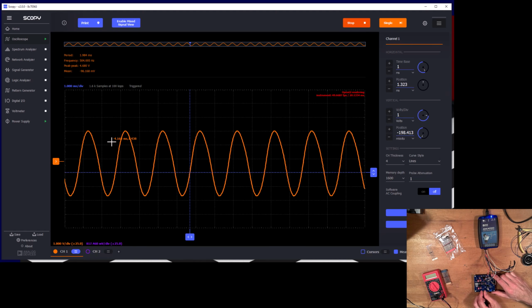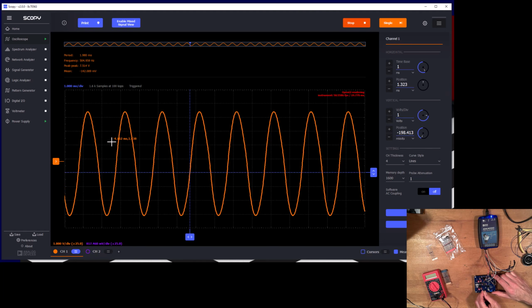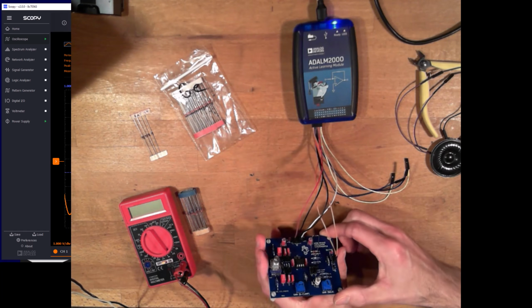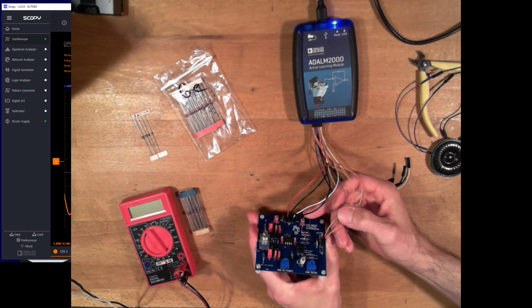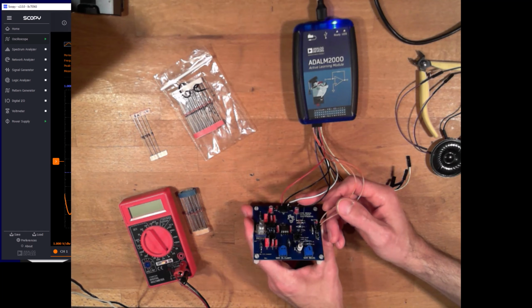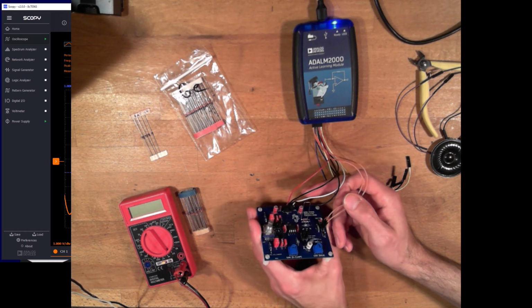Okay, now I'm going to mess with the gain a little bit here, and let's notice what happens. Okay, see how the bottom is clipping first? That's kind of intentional. I've actually soldered that Schottky diode in parallel with the silicon diodes that are soldered into the board here. So I wanted to play around with those different harmonic components here.